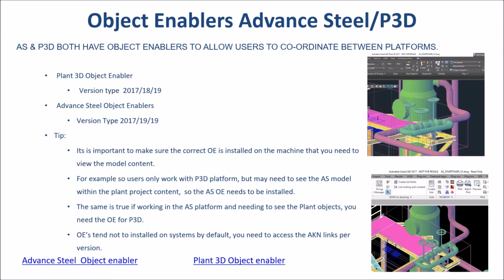So this is quite an interesting way of working, because sometimes, and me personally, I like to use some of the other tools inside Advanced Steel for drawing stairs and railings, for example, and I really don't want to bring all the original steelwork in via the SMLX, but I want to use that as a reference for me to model around, because I might need to adapt the stair or the railings or even the platform level, because the basic scheme is not what I would do as a detailer from a steelwork point of view.